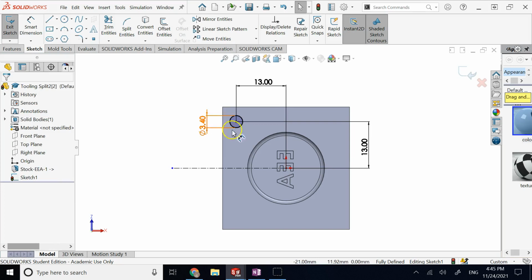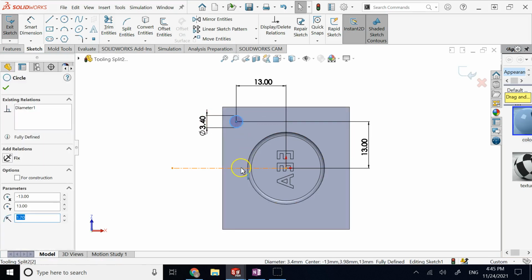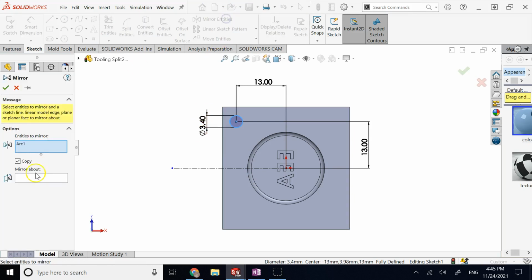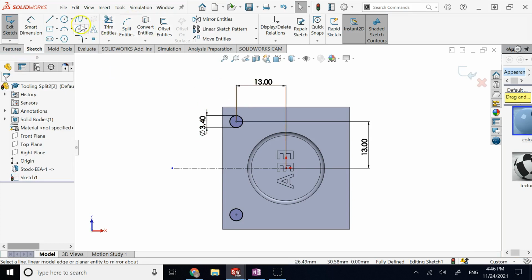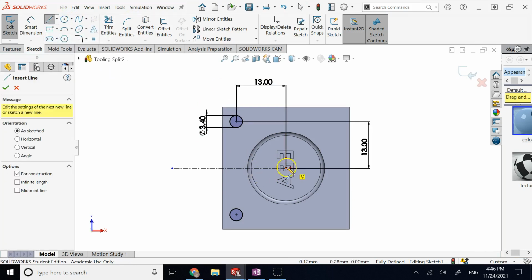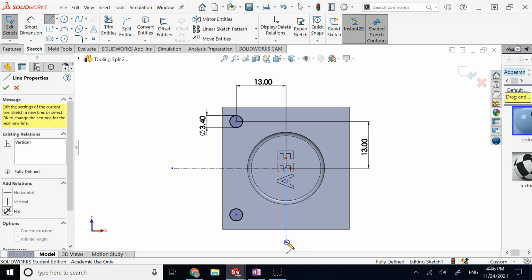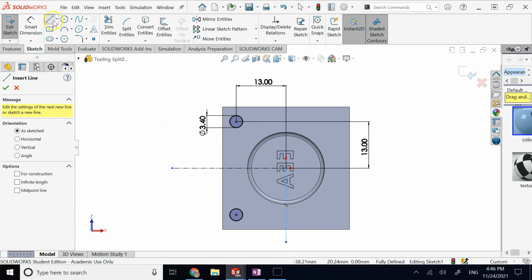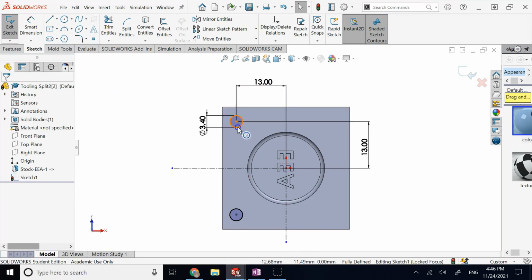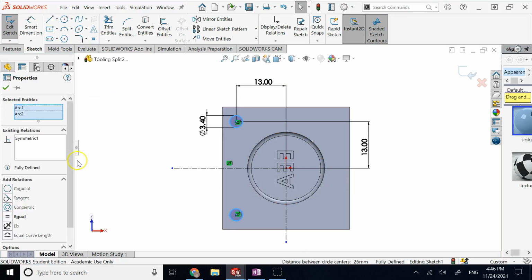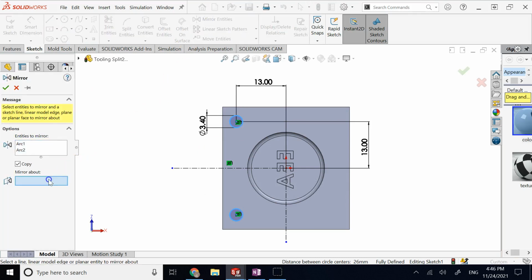Okay, so again, it all depends on how you are going to manufacture the mold. Is it a CNC, is it a 3D printer, or what? And what is the resolution of that machine in the X and Y direction? So here, as I said, I'm going to create these 4 holes, and then once I'm done, it is going to be a simple assembly if you want to see what's going on.